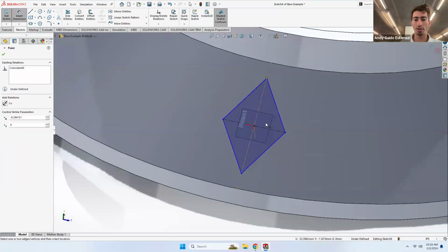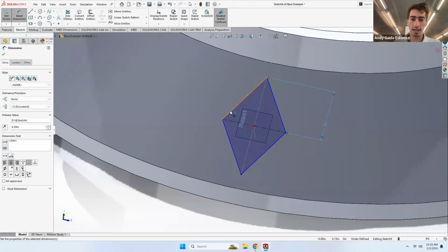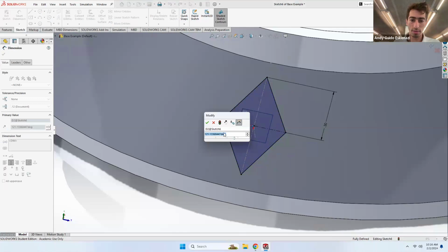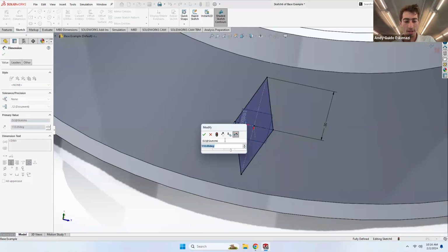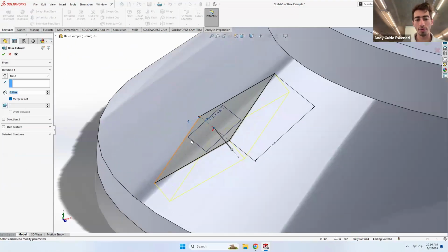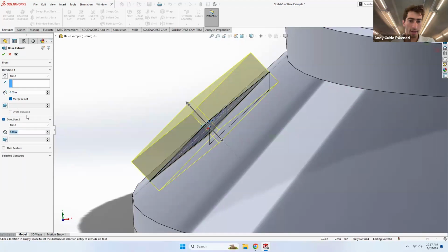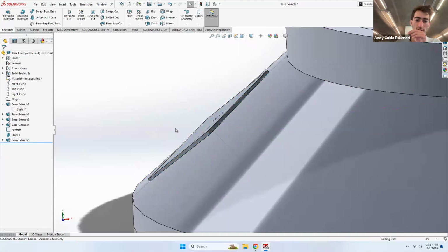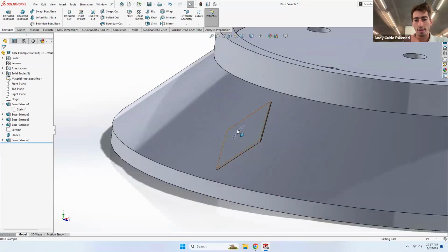So now all that remains is to fix the height in here to be maybe 0.3. And then I can define the angle here to be 110. Actually, no, 110 would be good. Let's see, 115. There we go. And then I can extrude this little rhombus downwards. Yeah, we can do 0.05 and then upwards by 0.01. That way, at least you can see the little row, and then I can hide that in there.